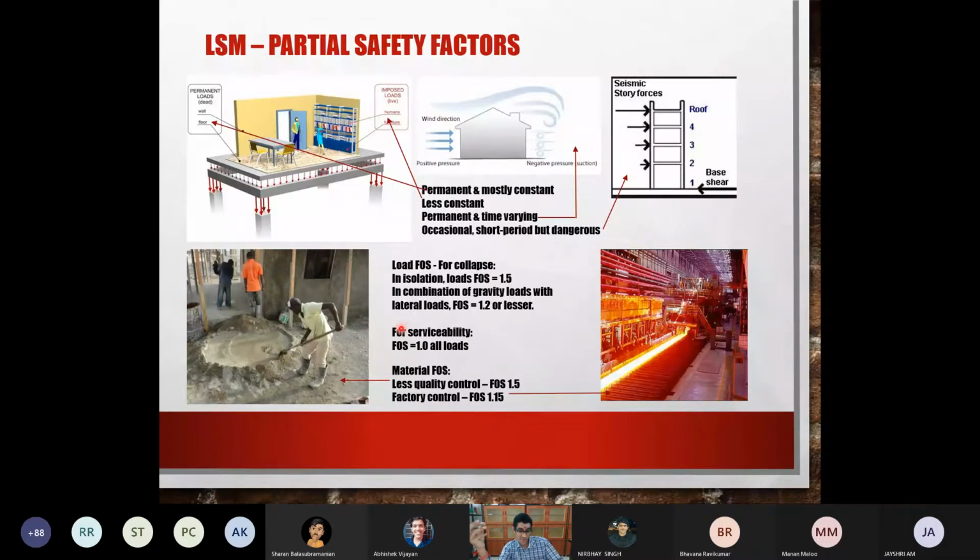Okay, so it is very, very unlikely that both of those bad events happen together. Only in a very historically unlucky situation that will happen, but it is not very sensible to consider such a situation for design purpose. Okay, so that is the reason that for most buildings they reduce this factor to 1.2, saying that it is very unlikely that both of these bad cases are going to happen at the same time. Okay, so that is the reason why it is reduced.